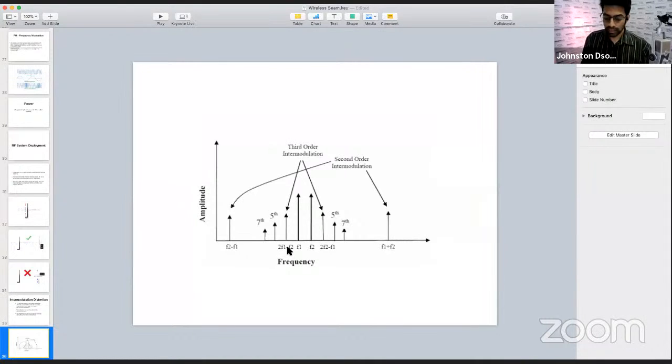So this is something that you need to do every day whenever you go to a new place. Even if you're working in a venue that has an installed system, you make sure that before your show starts, you do a frequency scan and make sure that whatever frequencies you're using are clean. Secondly, follow the grouping system of the manufacturer. Did you understand what I meant to say by the grouping system of the manufacturer?